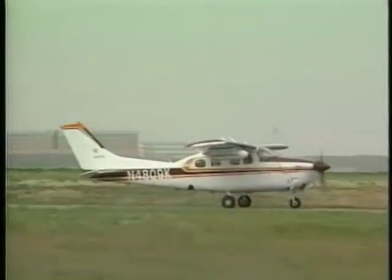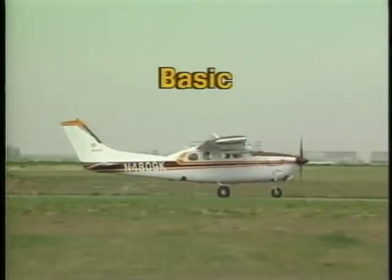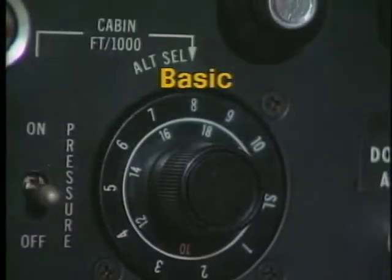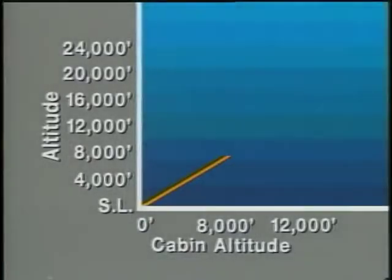There are two types of pressurization systems: a basic system and a controllable system. All you have to do with a basic system is turn it on. When the airplane reaches a preset altitude, commonly 8,000 feet, it will begin to pressurize. As the airplane continues to climb, the cabin altitude will remain at 8,000 feet until a second preset altitude is reached. Past this point, which is commonly 20,000 feet, the cabin altitude increases as the airplane climbs.